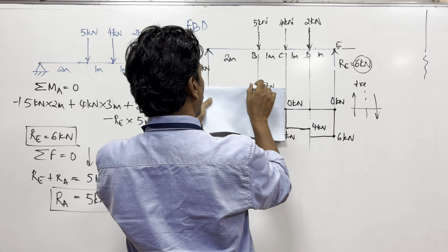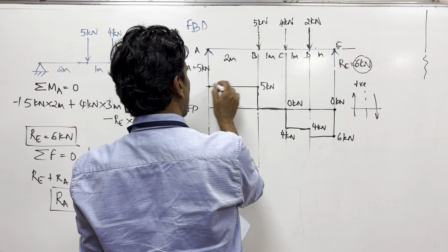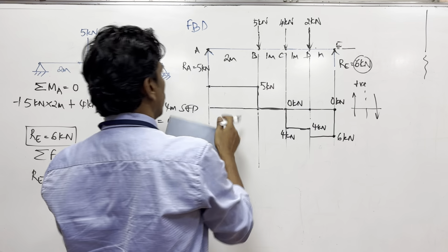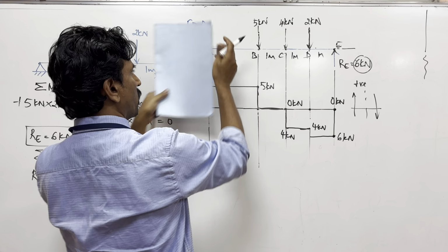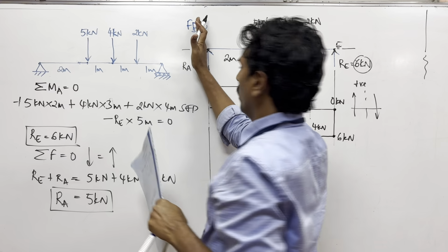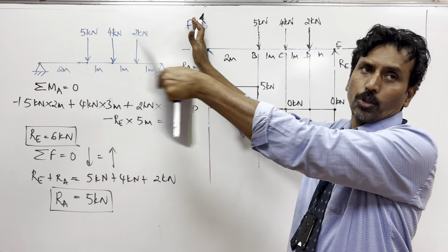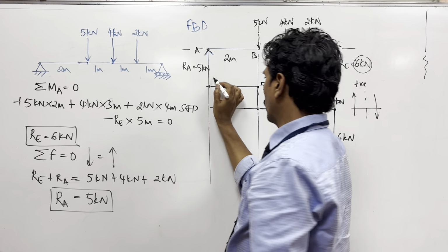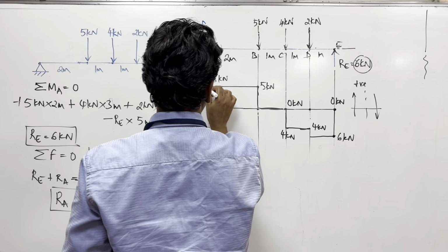You can find out either way, right or left side. So you are keeping like this, until this point you will only see plus 5. And again when you cross this point, plus 5 and minus 5 cancels out. If you imagine that the beam continues, any forces on the beam across this support, it is 0. So it drops from plus 5 kilonewton to 0.